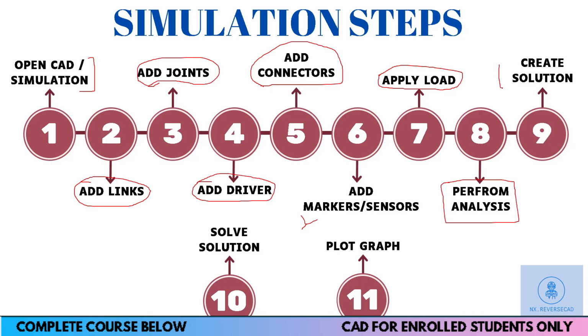Next step would be to create a solution where you will define the number of steps or the time in your kinematic simulation or dynamic simulation. At last, we'll solve the solution using the solver that I had discussed earlier. And at the last, we can plot the result using a graph. This graph could be anything, whether it is force, torque, displacement, acceleration, etc. So these are the steps that we are going to perform in our simulation, and this would be the order of the steps. We can omit some of the steps that we do not need in our simulation, but this is the workflow.